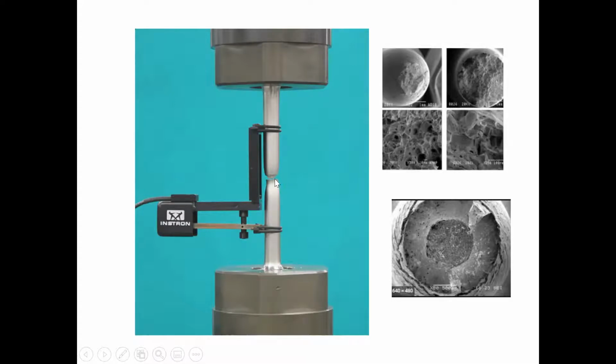And when the bottleneck starts to form, you can guarantee it's going to fail there. Once this happens, it's never going to fail up here or down here. You can be sure of that. It will always fail here, right between the gauges. This is the elongation, the device that measures the elongation. It's called a clip gauge. Here's the top clip and here's the bottom clip. And there's some electronics made by a company called Instron. That's the company that makes it. Their emblem shows two people pulling a piece of rope apart. And here's the cable going off to the computer.